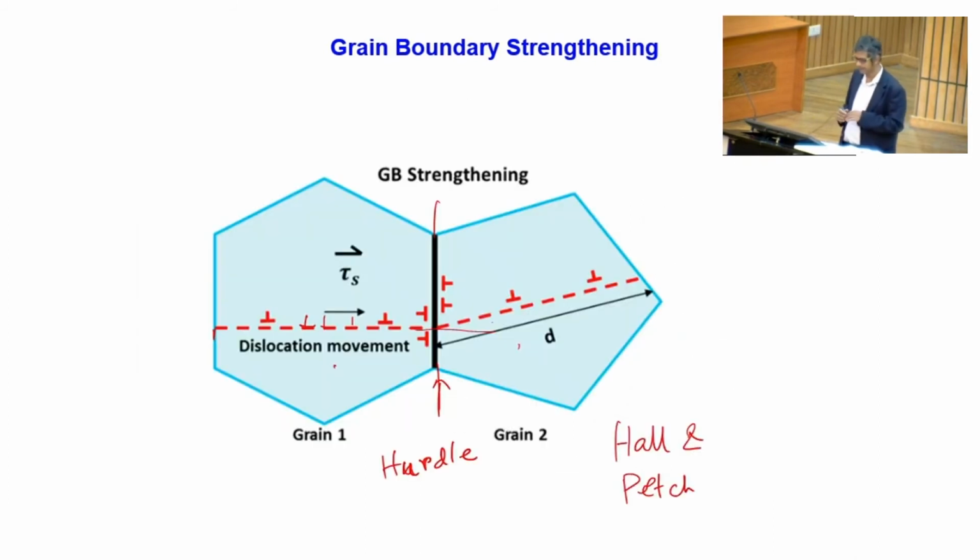So I'll go back here. Okay, that's mainly because of these aspects. Grain boundaries provide an obstacle to the movement of the dislocations. Remember, plasticity or plastic deformation is dictated by the generation and movement of the defects. The more the movement of the defects, the more slip steps are created at the surface, the more the plastic deformation. So if grain boundaries are not allowing the dislocations to move, the material will not deform. So the material will show higher and higher strength. That is something very unique because of the grain boundaries.